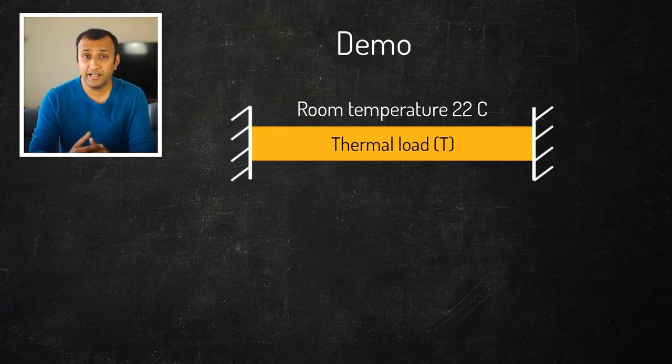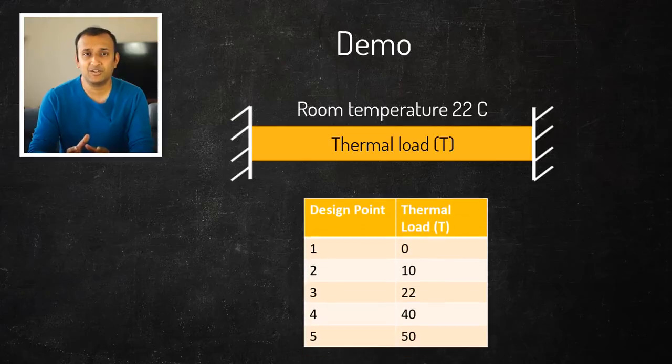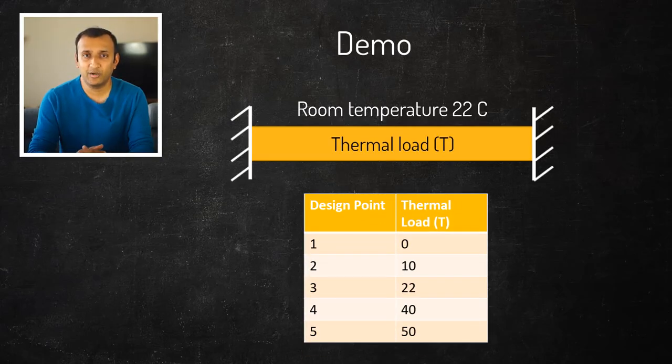The goal of this study is to see how the mode frequencies of the bar change with the thermal load at 5 different values. We'll perform a parametric analysis to run a series of simulations and study this trend. Each simulation is called a design point.